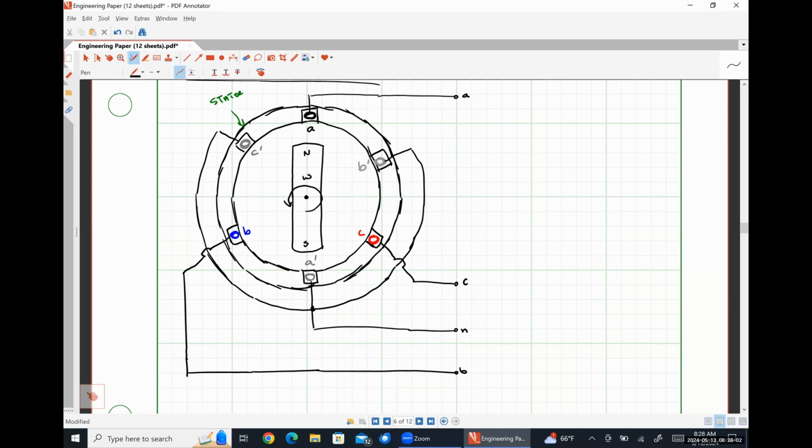And then as our magnet rotates, the amount of flux that's passing through coil A is going to gradually decrease until we have a maximum value of negative flux because our field has changed direction. And then it's going to continue cycling between maximum, gradually decaying down to minimum, gradually increasing up to maximum over and over again.